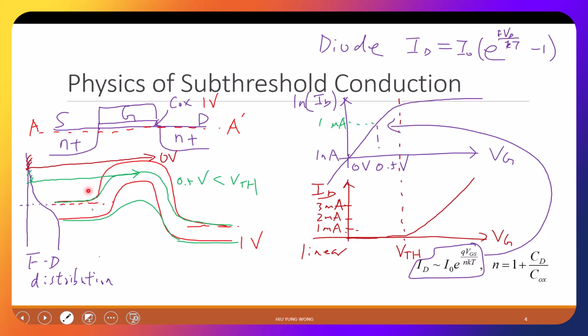And for the gate region, it goes up because of many things, including the so-called gate work function, etc. But one important thing is the gate bias, the gate voltage. We start from 0, or just think of it as negative. This is the red line. We make the barrier very high. So as a result, your electron cannot go through this barrier. Right? This is very classical.